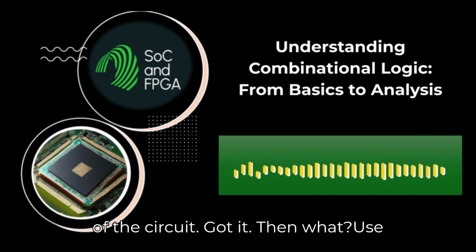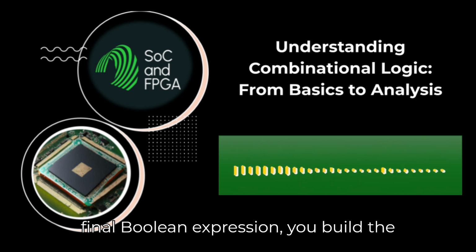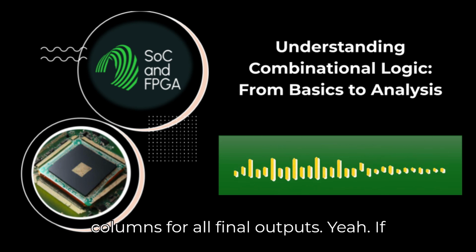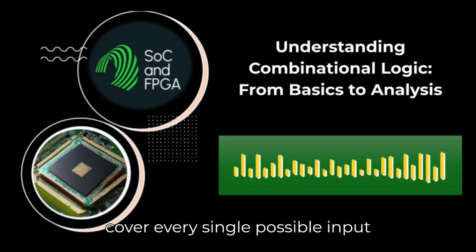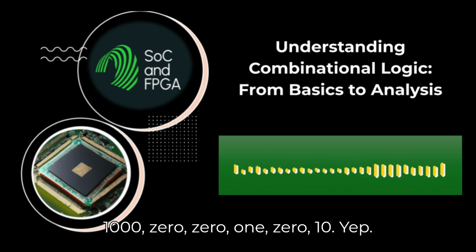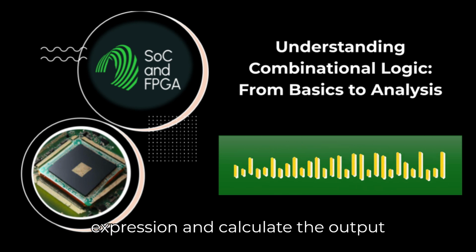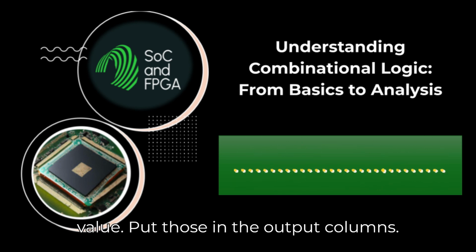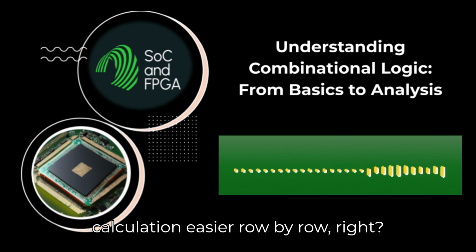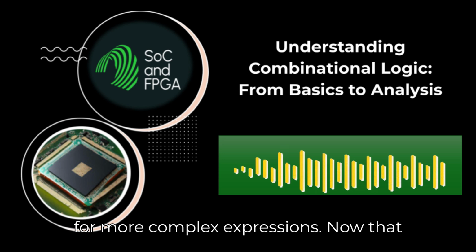Got it. Then what? Use that equation. Step 3, constructing the truth table. Now that you have the final Boolean expression, you build the truth table. Columns for all inputs, columns for all final outputs. If you have n inputs, you'll need 2^n rows to cover every single possible input combination. List all possibilities: 000, 001, 010. Yep. Then, for each input row, you plug those zeros and ones into your final Boolean expression and calculate the output value. Put those in the output columns. You could also add columns for those intermediate T1, T2 variables to make the calculation easier row by row, right? Absolutely. It helps break down the calculation and avoid errors. Very useful for more complex expressions.